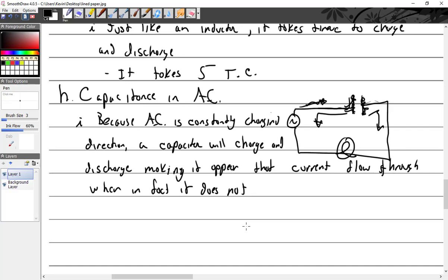Let's see. We've already talked about this. When voltage is applied, maximum current flows instantly, immediately. This is because the capacitor plate easily takes a charge, which is a flow of electrons. Max current happens as soon as the voltage moves from 0. So right away, I already wrote that. In an AC waveform, max current is at 0 degrees. As electrons build up on the plate, the capacitor opposes additional current flow. There is zero current flow and the voltage is maximum. Do I need to write all that? Okay, good.